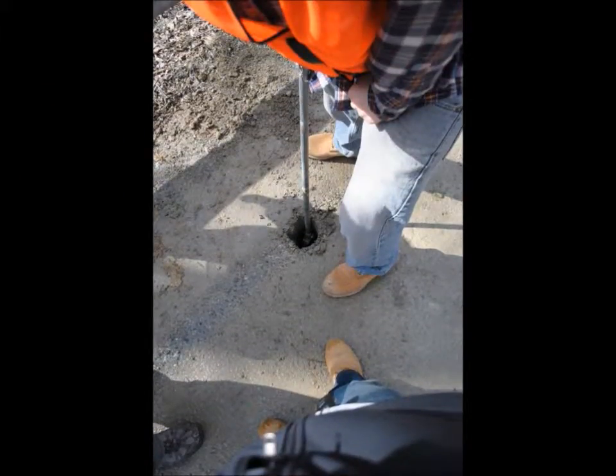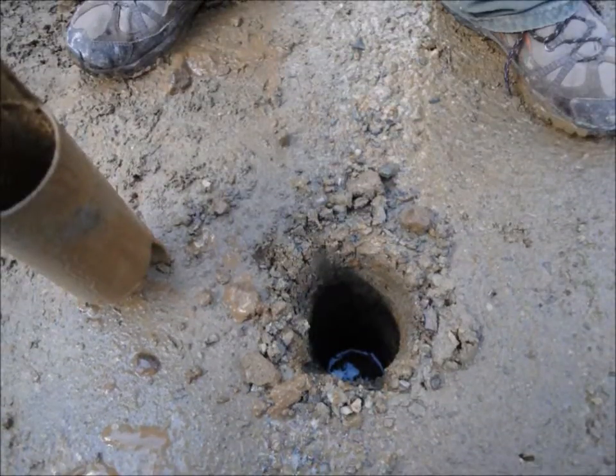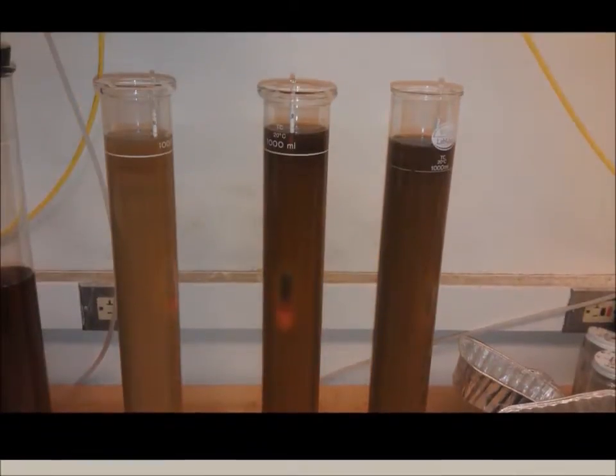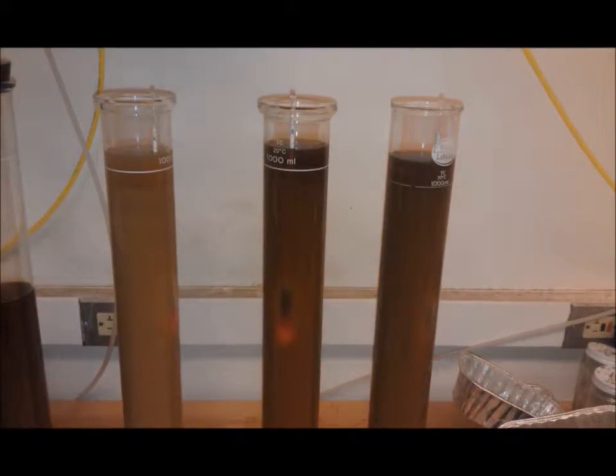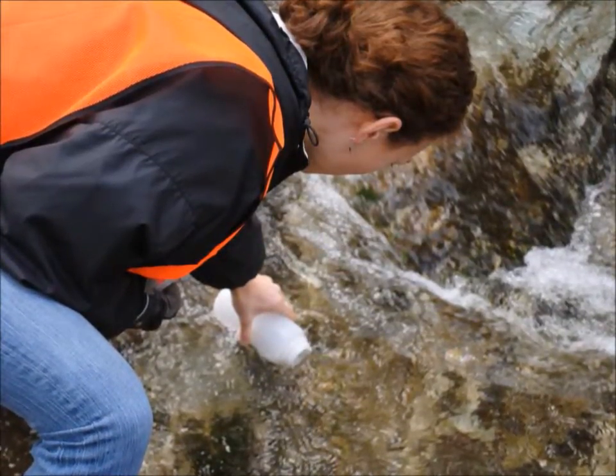Next, boreholes were drilled using a hand auger. Here you can see the high water table which was mentioned earlier. The collected samples were analyzed through sieve and hydrometer tests to determine grain size distribution of the soil. Using this data, it was determined that the current soil was not adequate backfill and therefore could not be reused, and a more permeable backfill must be introduced.